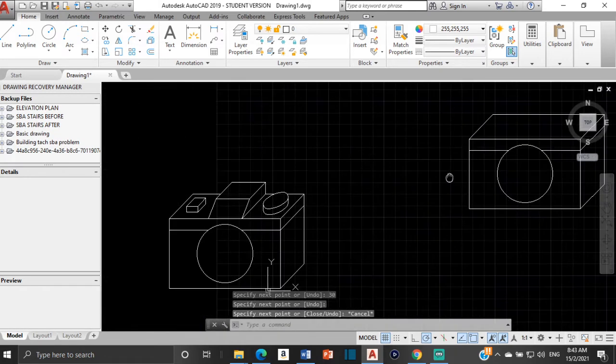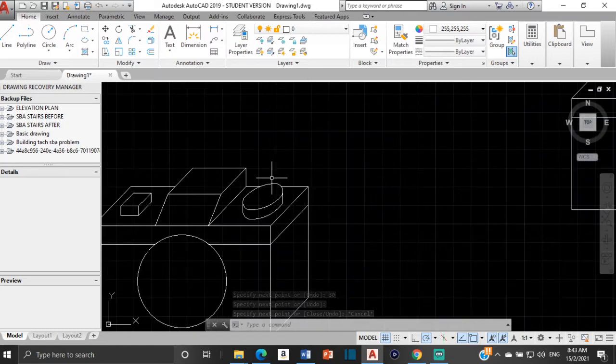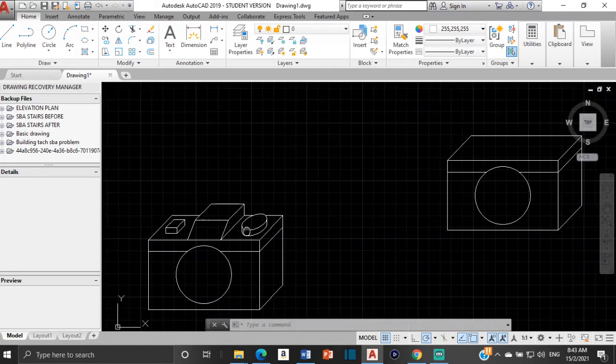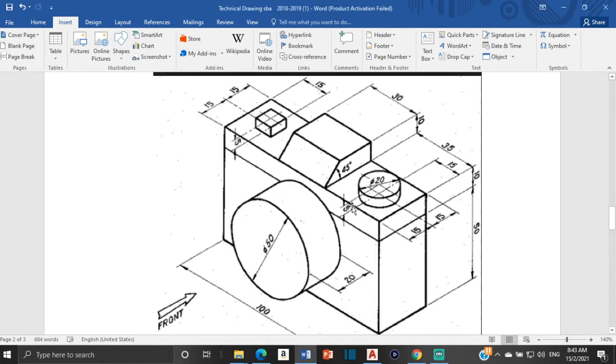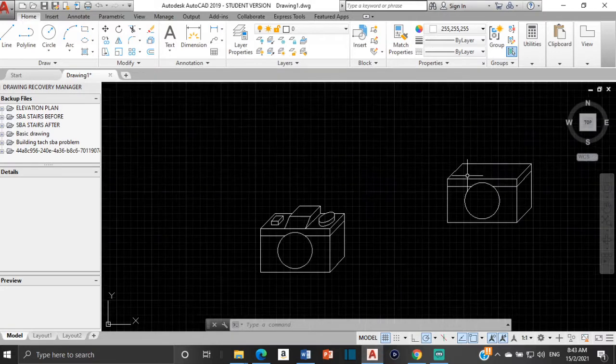So now what we need is this button here, and then this button over at this side. If we look at this button right here, the center of the button is 15 up and 15 over here, and we'll get the center of the circle that makes the button, and it has a diameter of 20 millimeters. So let's get to that drawing.